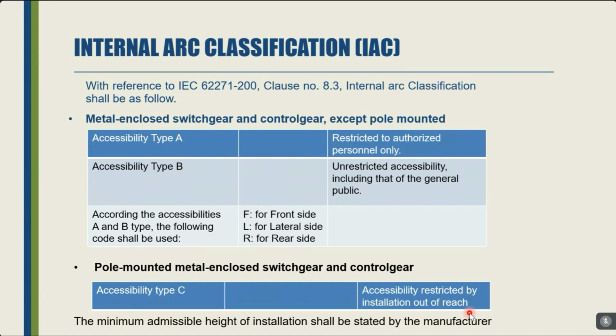So here, for public and animal safety, the switchgears are installed at a height much greater than the reach of a human being or animals, from a safety point of view. The minimum admissible height of installation for each switchgear shall be stated by the manufacturer. This is manufacturer standard, and as part of the requisition or offer, they provide the admissible height for the HT switchgear.